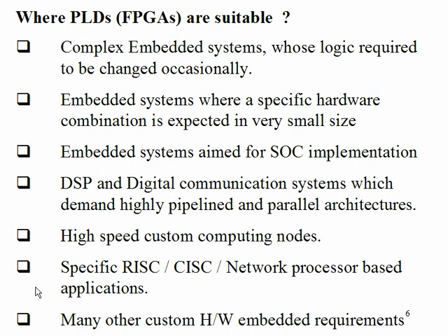Few clock cycles, correct. That's one major important difference. The name itself gives the meaning. Reduced instruction set computer means the number of instructions is reduced, and the amount of job you are doing for one instruction is also reduced. In a reduced instruction set computer, an instruction typically performs a small job in a very small amount of time. What do you mean by that? Maybe one clock cycle or two clock cycles, like that.